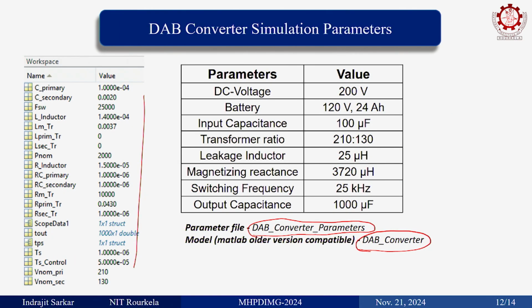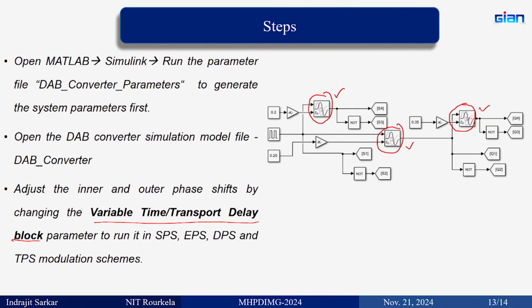So, the simulation parameters are also given here, the same simulation parameters, and this file will be shared. What you have to do is run it; we assume that all of you have MATLAB. I have saved this MATLAB file in a lower version of MATLAB, so that whichever recent MATLAB version you have, you can run it, even online. I do not know whether this time step will work; you have to keep the time step 10 to the power minus 6 or so.